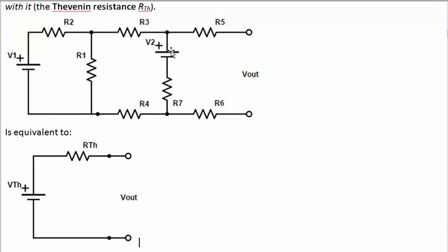Then we can find the voltage source by taking loop equations. Often it's useful to use the superposition theorem, which you may remember from second year, to do this as well, which is to just turn on one voltage source at a time and figure out what that would produce on the output, then add them up, because voltage is going to add linearly due to all the linear elements and linear equations that we're writing here.